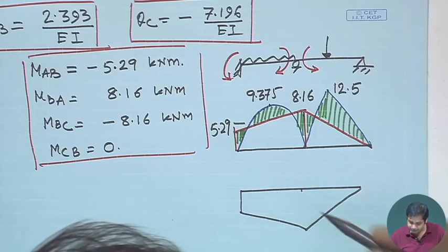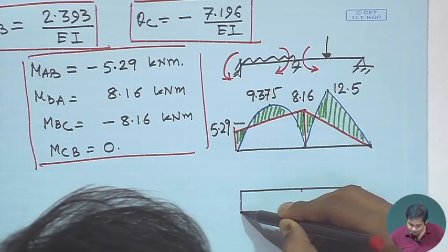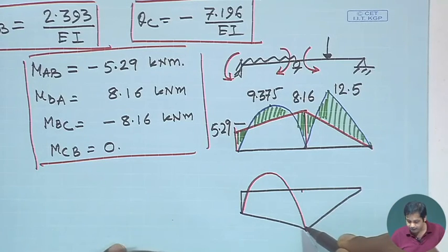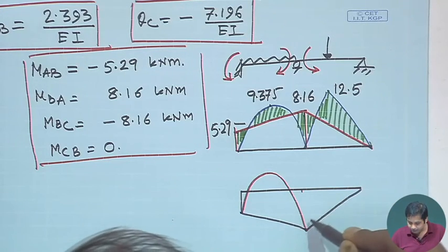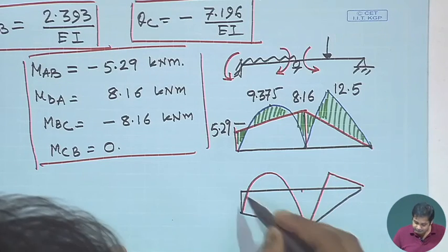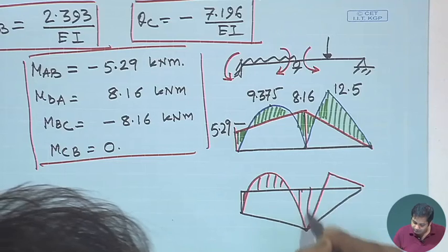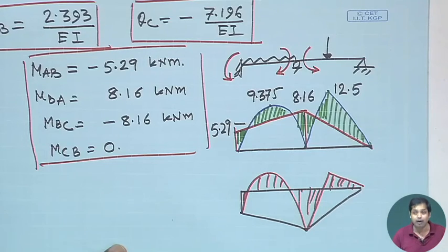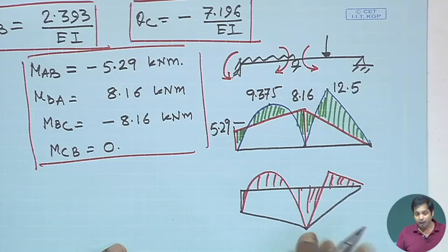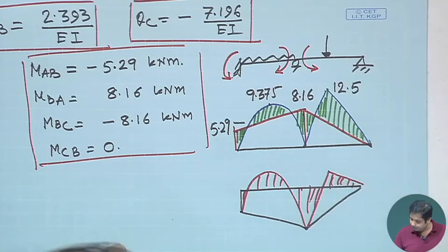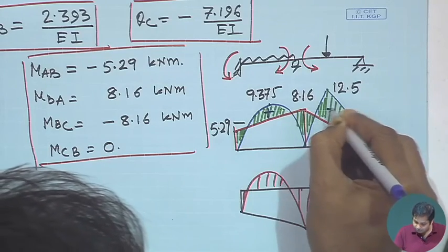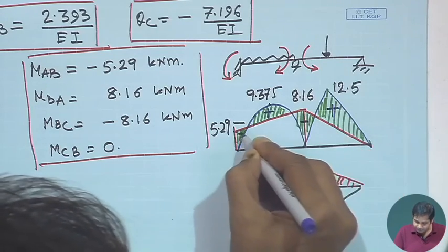Okay, something like this, something like this, and then from that we can get something like this. Okay. So, in that case this becomes your bending moment diagram. We check this bending moment diagram, do not take it for granted. Now, you look at this: all this is positive, and this becomes negative, this is also negative.